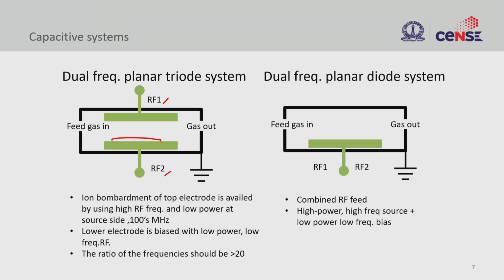and then you can use your gases that are fed through the system to generate the plasma with this dual frequency configuration and do the etching. So what we avoided by using dual frequency is etching of one of the electrodes, and the sputtering of one of the electrodes itself. So this is how this was handled.